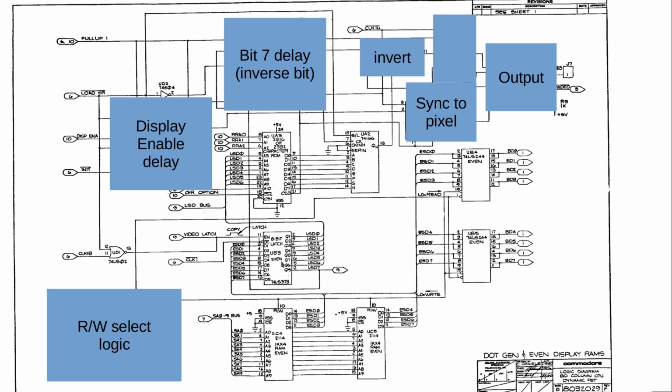and those output bits go to the latch that takes the data after the first half cycle before the CPU takes over the bus, and presents it to the character ROM. Then when the character ROM is done, it has the output on the input of the shift register, and then the shift register can load that to the further output. And those are the data buffers where the CPU can access the video RAM. The other stuff is more or less